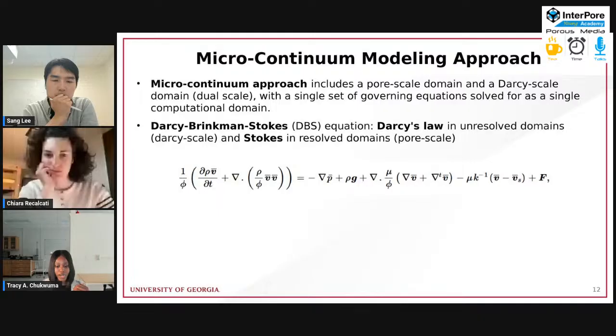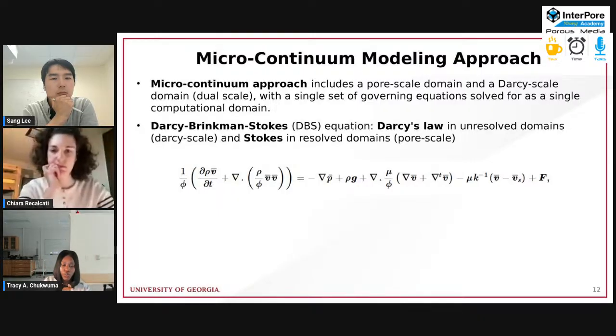If you grid the structure and identify a cell as purely porous, then the equation that is going to be solved in that particular cell is going to be the Stokes equation, which is for fully resolved domains. And then if you identify another phase as maybe the microporous phase that we had, which is a mix of both solid and fluid aggregates, or porous space. It's a mix of both. For those microporous phases, Darcy's equation will be solved in those spaces.